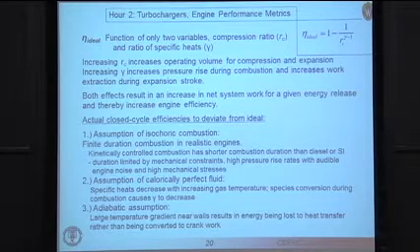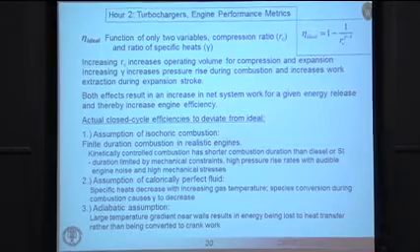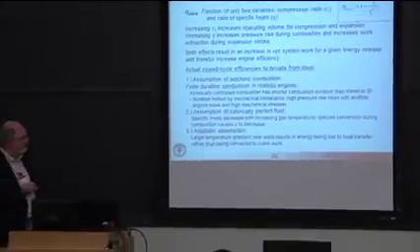So that's assumption one. Assumption two is we don't have a perfect fluid. The specific heats decrease during the compression process because the gas temperature is increasing. So this causes a problem. It causes the gamma to vary. Also, there's the issue that the combustion gases themselves have a different composition than the reactants, again with a different gamma.